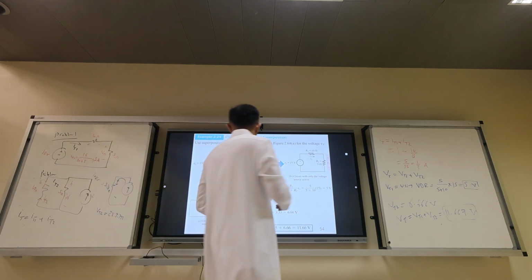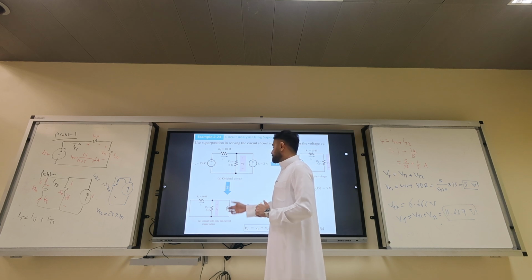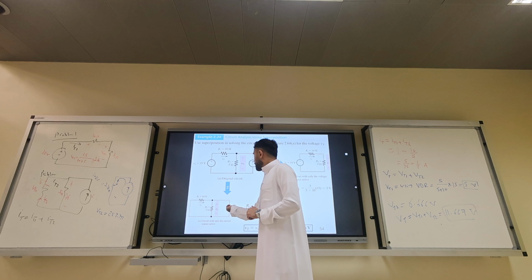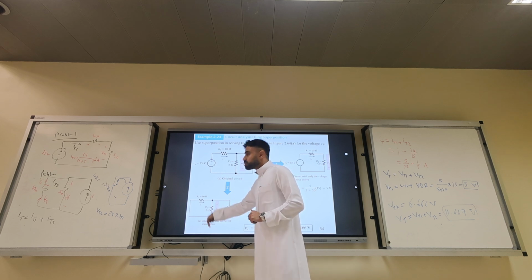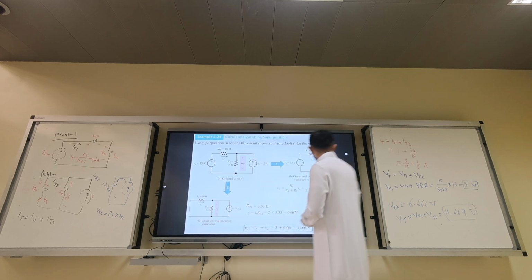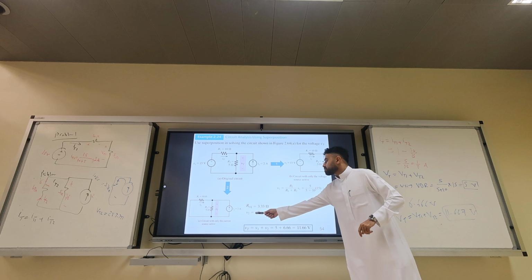Well, to calculate the voltage in the current source, the only way to do it is KVL, or find the parallel combination and let the 2 amp go through the resistor and V equals plus IR. And that's what we did here, the 6.66. It's 2 times R equivalent.